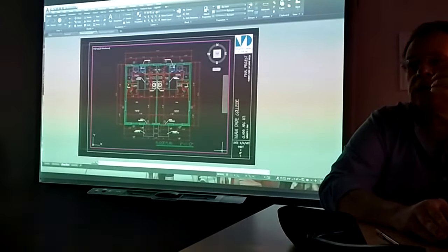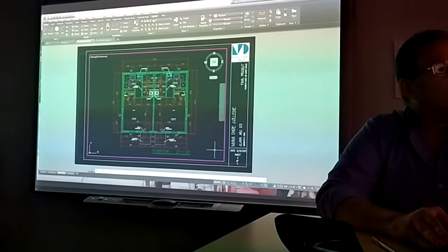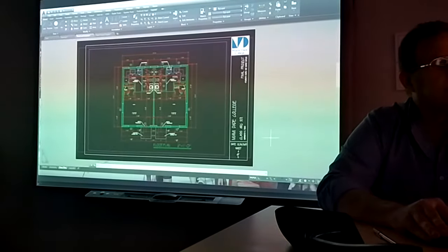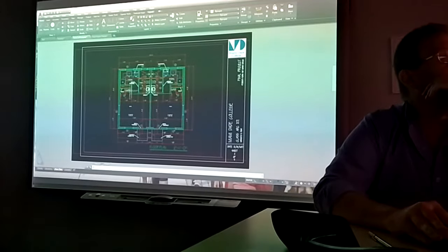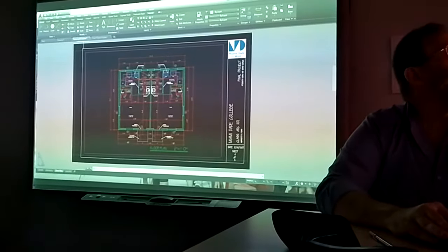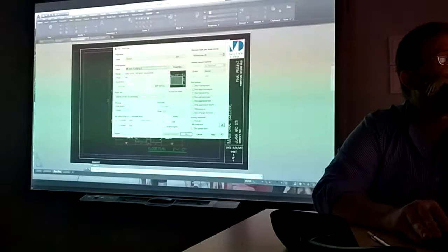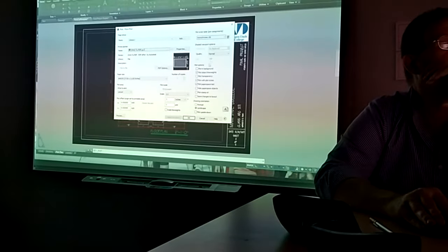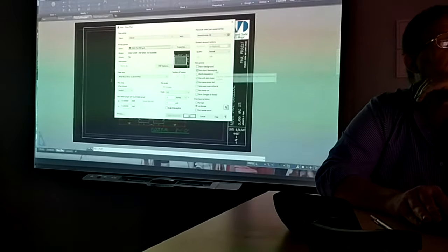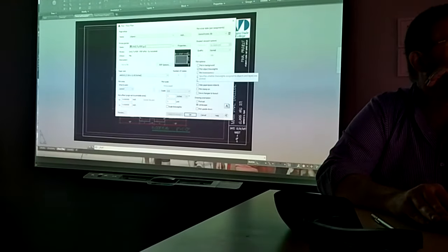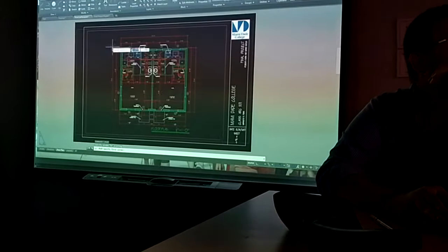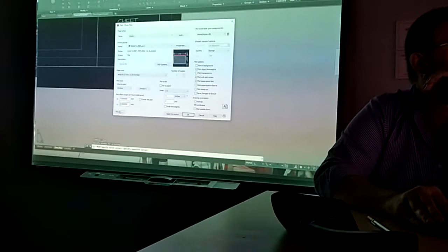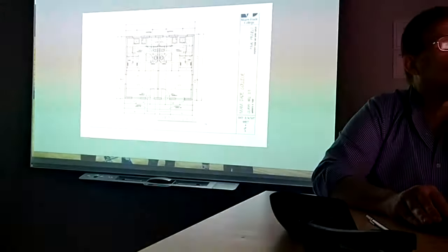That's one thing that you have to coordinate, every drawing. So, it's all there. So, I want to deactivate this outside 2 times, that's it. Now, if I wanted to see the way it looks printing, go to plot, continue to plot single sheet, and you could create a PDF if you like monochrome. If you have object line weights, make sure you click in here. Change this to window, and let's do a window the way I told you, so that you can have the 1/2 inch space in between the edge of the paper and the border.